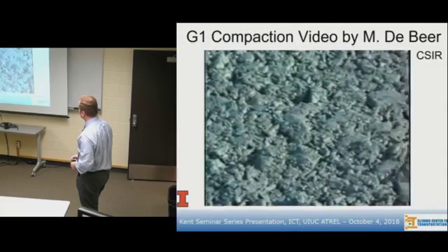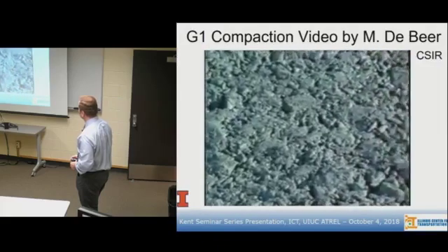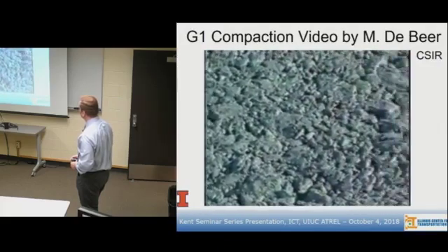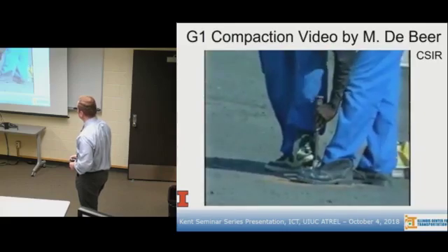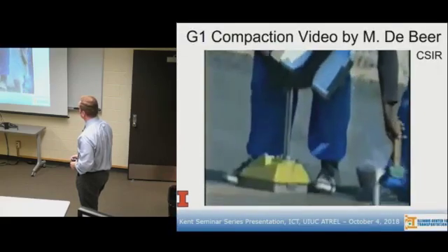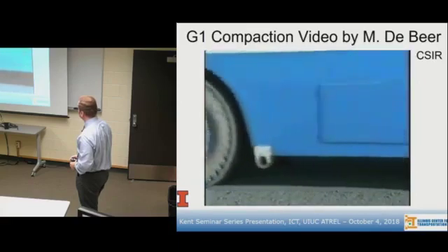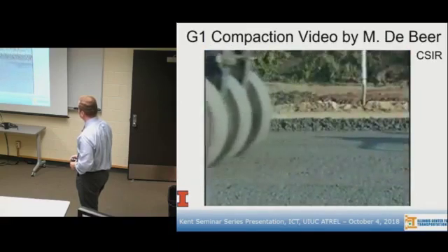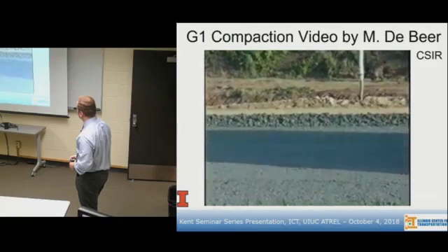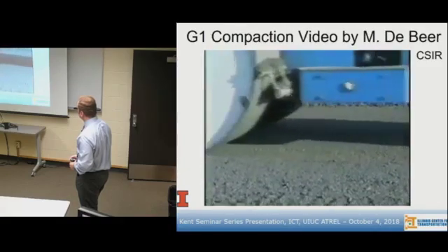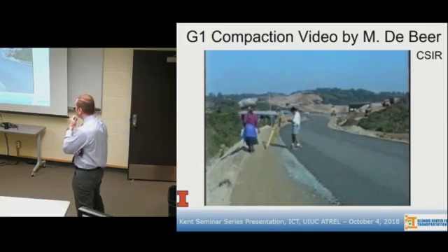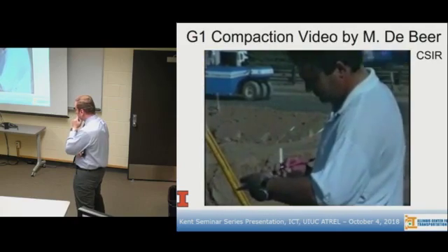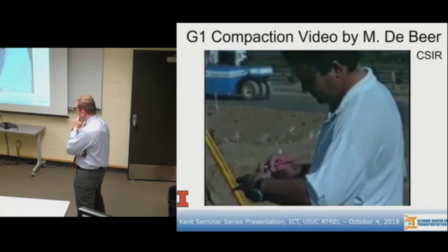Caution should be taken not to crush the particles and hence alter the gradation or to deform the surface. The density progression should be randomly monitored after each roller pass to quantify effectiveness and to identify non-productive rolling. The process continues with pneumatic tired rollers in combination with static steel-wheeled rollers to a density of at least 85% of solid particle density. The layer should have a well-knitted and uniform appearance with the correct longitudinal elevation and cross-sectional form.